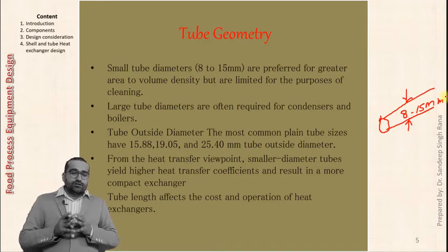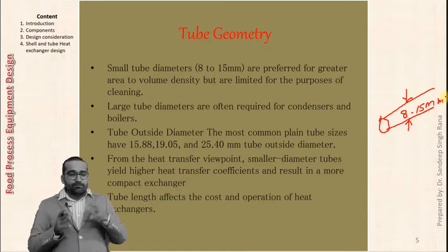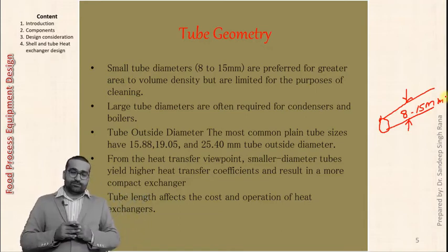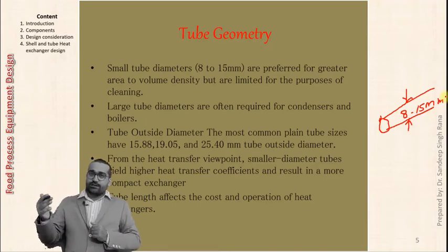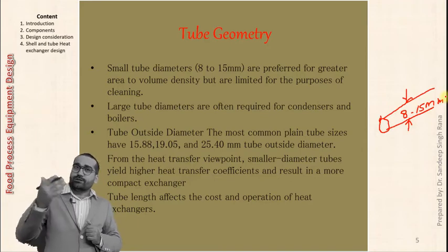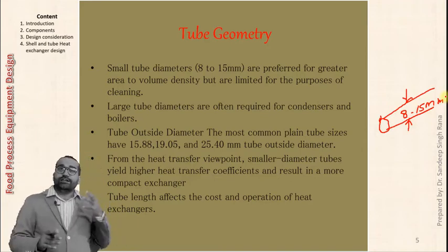And the most efficient condition of a heat exchanger is to have the maximum number of tubes in the shell to increase the turbulence. Turbulence we have talked about previously. Again we are talking about turbulence because turbulence is very important to increase the heat transfer rate.